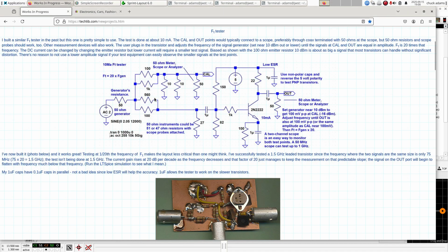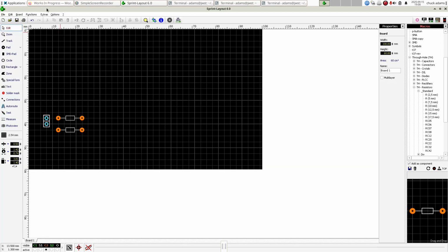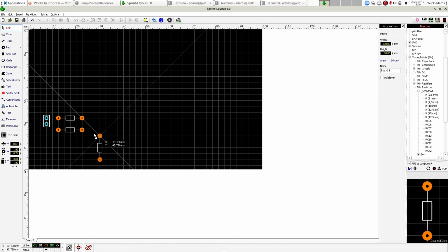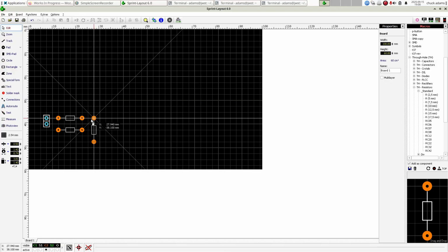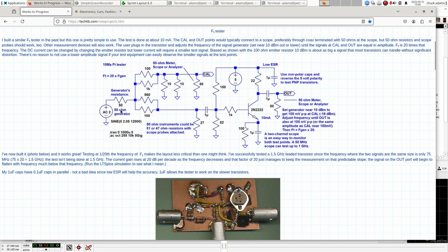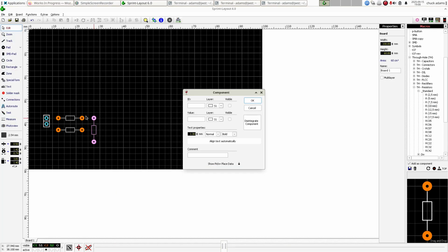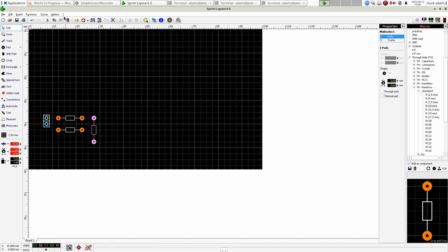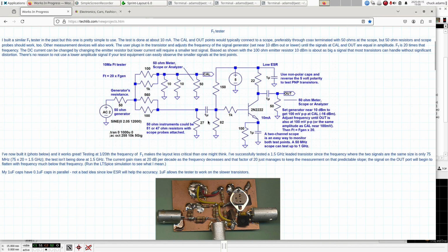So now I've got 560, 100. Now I've got a 27 ohm resistor. Now we'll just put it vertical like it shows in the schematic. So I rotate this 90 degrees, and it's lined up with the pin, the input pin here. Well, I'm going to put the input pin here. So all this lines up. So I'll do that. Next comes this 1 microfarad capacitor.